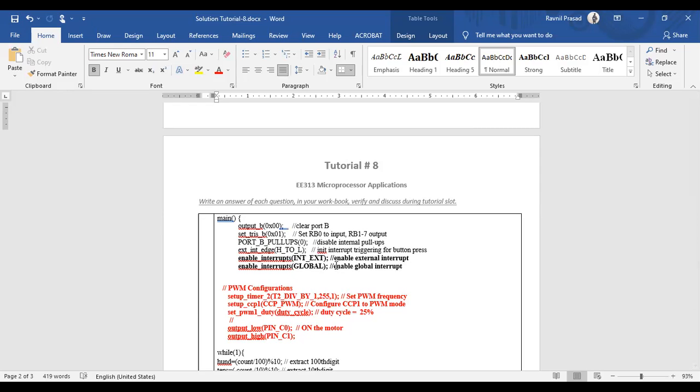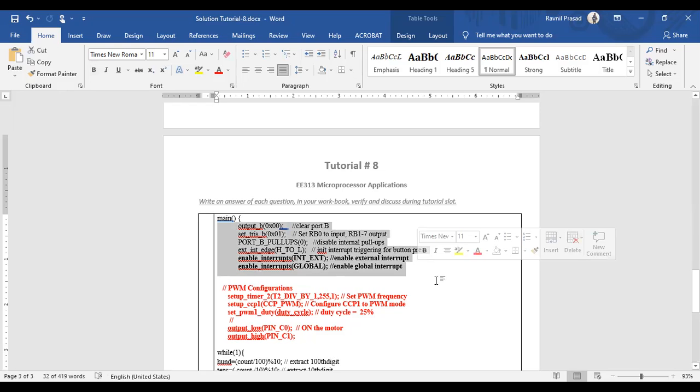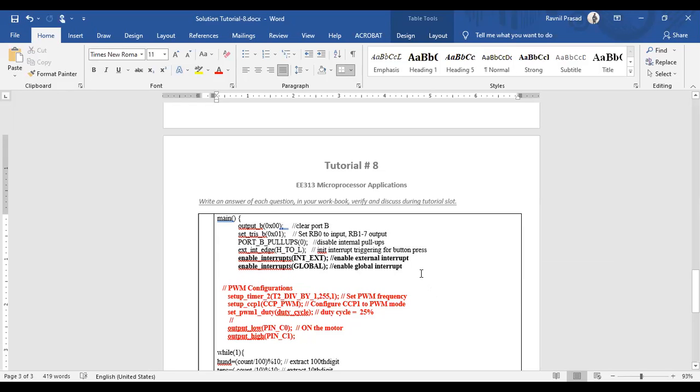So keeping that in mind, we start off by initializing the proximity sensor, right? So in this particular case, we have to attach the external interrupt to the proximity sensor. So this is the code that we have to write in order to enable the external interrupt and attach it to the pin to which the proximity sensor is connected, right? So we have been dealing with the external interrupt so far. So I believe all of you know how an external interrupt works by now, right?